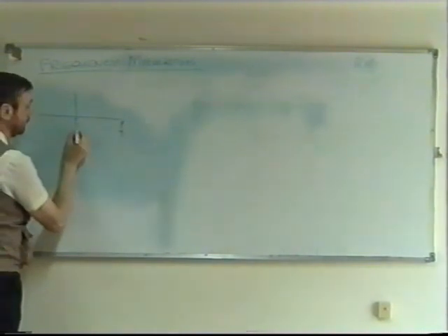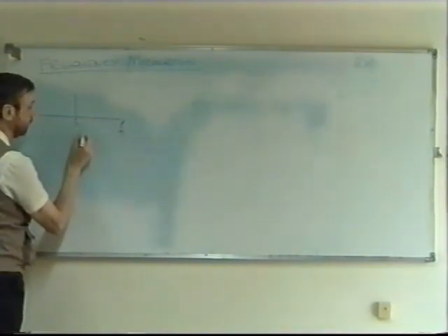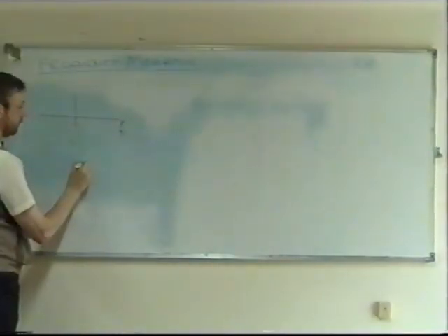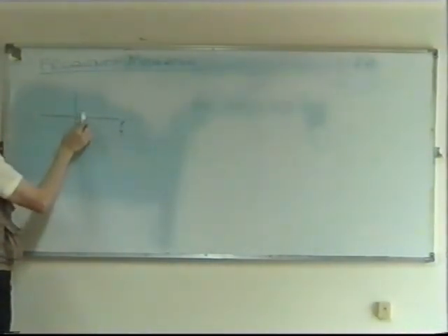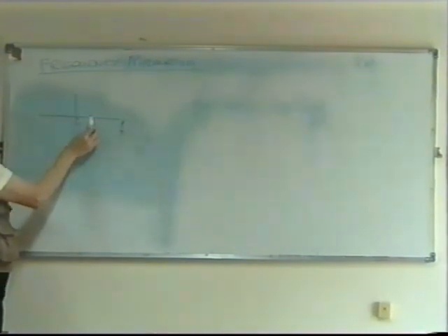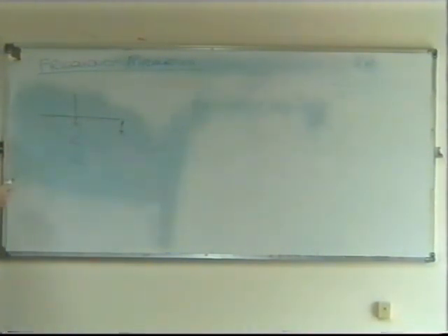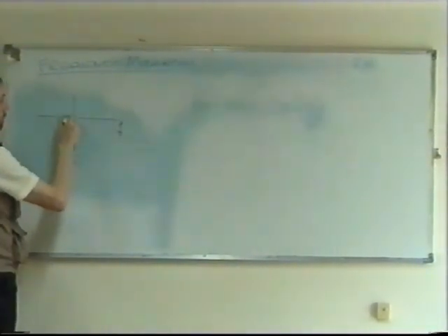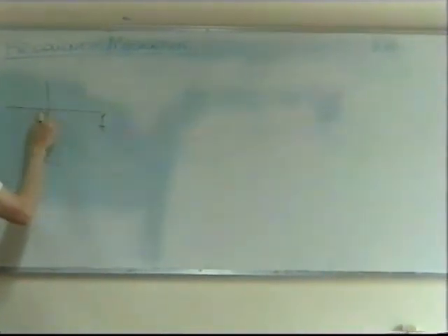For example, if what I'm drawing here in green is my modulating signal, then it causes the carrier to increase, decrease, increase and decrease according to the amplitude of the signal. One half cycle, the other half cycle. So the frequency of the carrier is changing, not its amplitude.